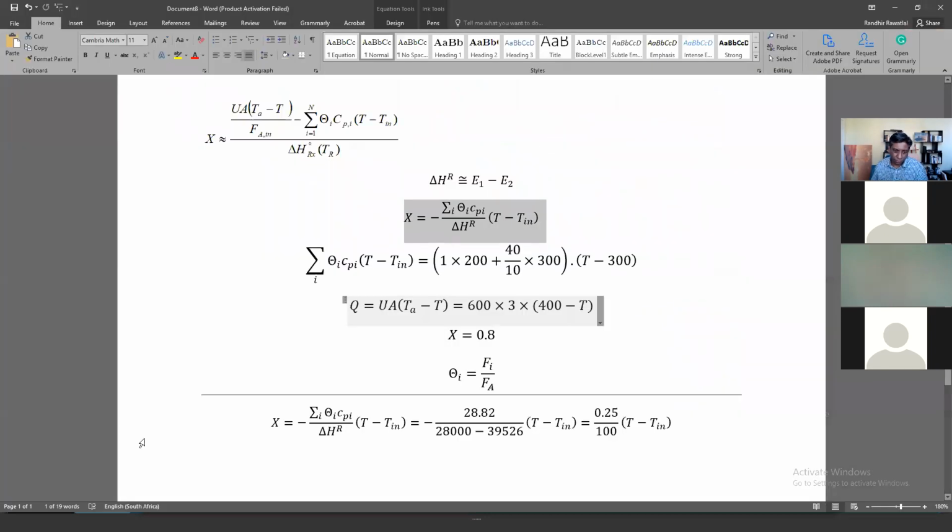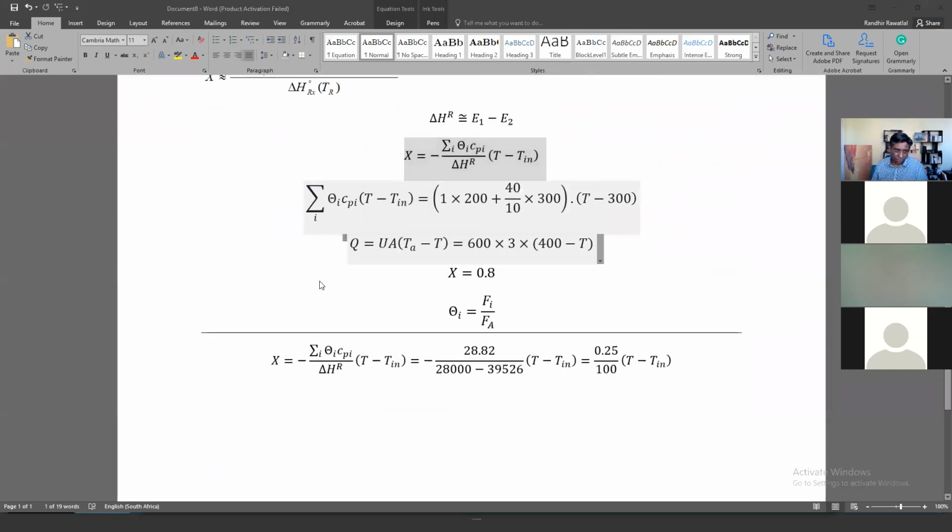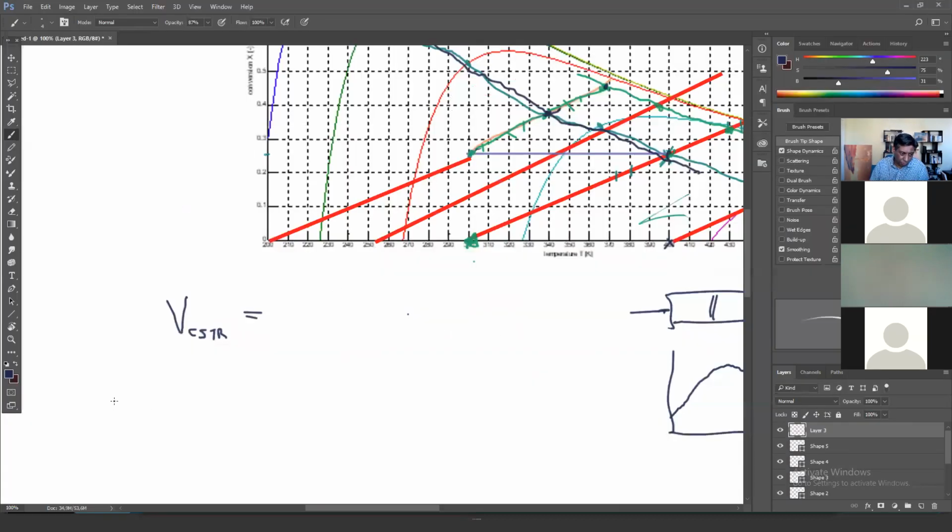So we know for the CSTR, FA naught X equals RA V. So VCSTR is FA naught X over RA.